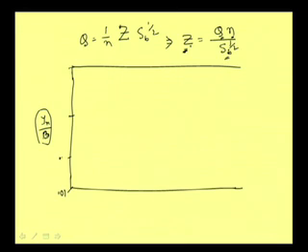So, it is 0.1, 1 and 10, that way we are dividing it. On this side we are writing the section factor, that is A R to the power 2 by 3. Area has a dimension of L to the power 2, that means length square. R, the hydraulic radius, has a dimension that is also length, so it will be length to the power 2 by 3.